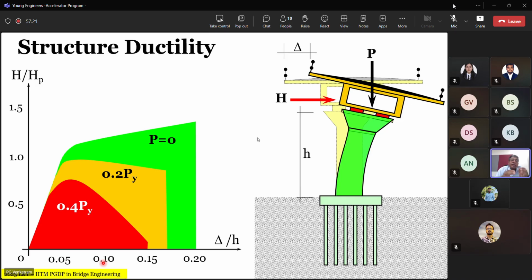So in this sense, for all lateral load caused deflection, the moment you increase the axial load beyond a certain limit in terms of its capacity, you will find that the failure takes place much earlier than expected, thereby indicating to you that the planned ductility, which is there when you choose your material and your steel type, you've chosen the structure ductility, but you don't get it because of your design decisions, which link to the size of the section that you adopted.